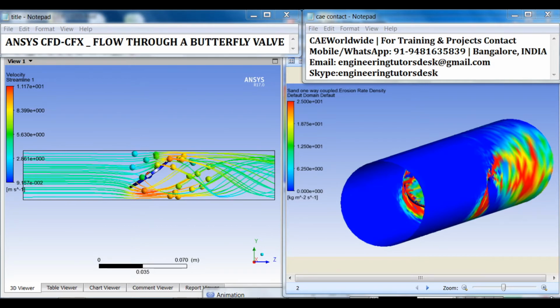In our example, we are considering a butterfly valve in the pipe structure to examine the behavior of fluid across the valve. A butterfly valve is a valve which can be used for isolating or regulating flow. The closing mechanism takes the form of a disc. Butterfly valves are commonly used in industrial applications to control the internal flow of both compressible and incompressible fluids.